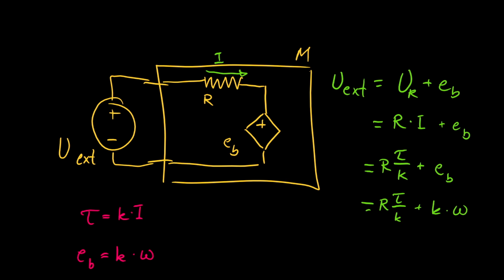So essentially we could end up with an equation that is some k tau times tau plus k omega times omega. In this case, k and k omega is the same. But now you see that the voltage is a combination of these two variables, tau and omega, times these constants. So now it's a matter of measuring and finding those constants.